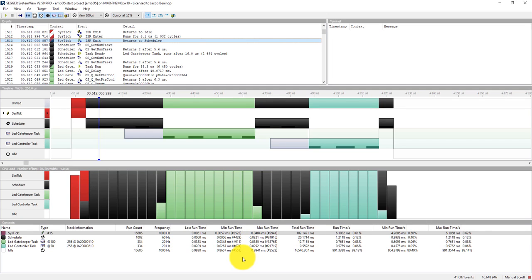There's also then some very useful information from a real-time standpoint. A lot of times we just develop our code, we cross our fingers, and we hope for the best. We assume that we understand the timing of the different tasks throughout our system. It's very possible that we could end up with contentions or areas where our code is taking longer to execute than we expect it to. As we're tracing our application code, we're getting timestamps back and the events of when we enter a task, exit a task, and the events that are occurring inside that task.